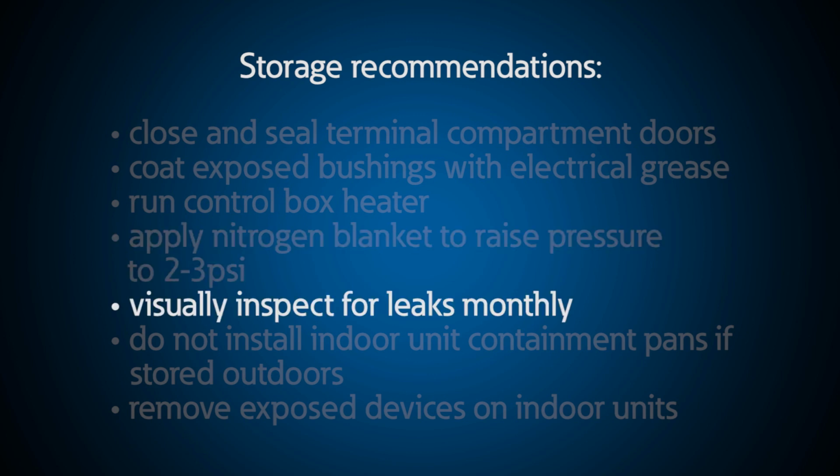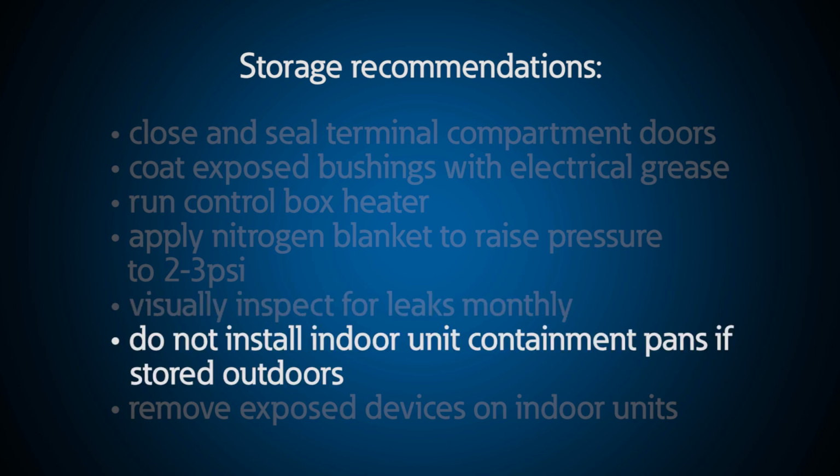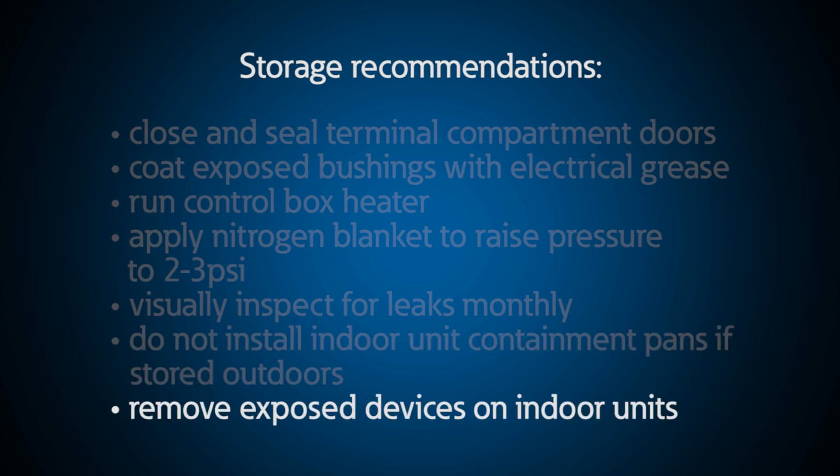On a monthly basis, visually inspect the transformer for leaks, including a visual check of all gauges. If a unit is rated for indoors, containment pans should not be installed if it is temporarily stored outdoors. If the unit is rated for indoors and has exposed electronics, the devices must be removed or properly covered.